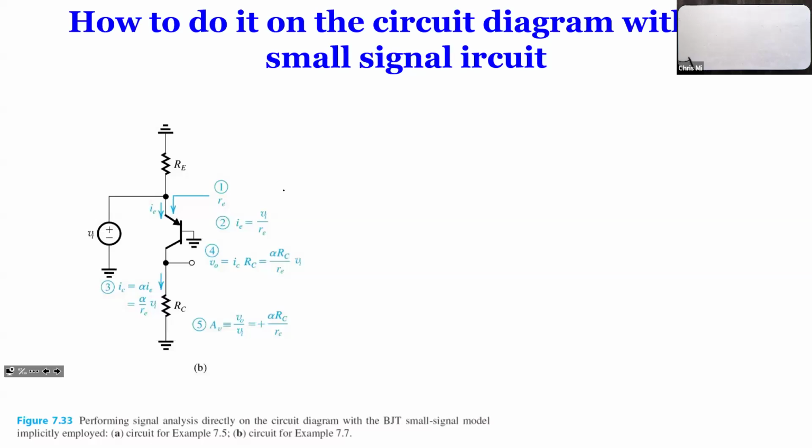Why do we do, when there's a BJT with a DC and AC, why do we do DC first? Do we find something that helps us with AC? Well, because you have to do DC to find GM and R pi, or RE. DC first so that we can find those two. And also often you do DC because you want to make sure it is in active mode.